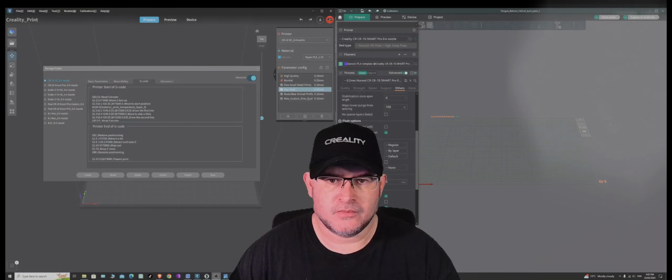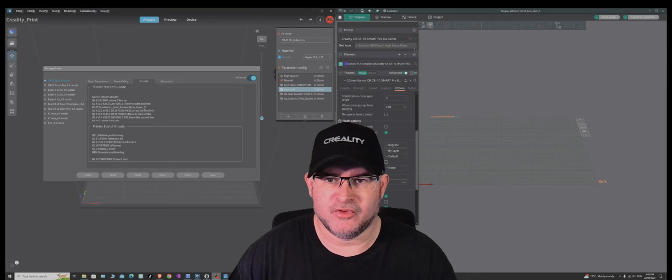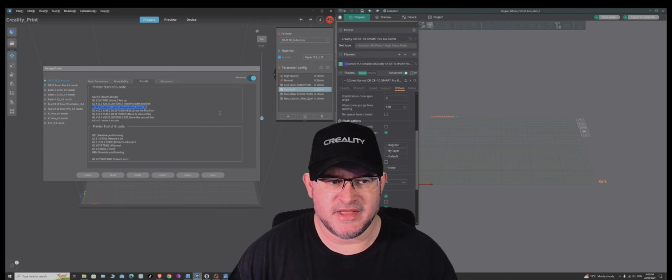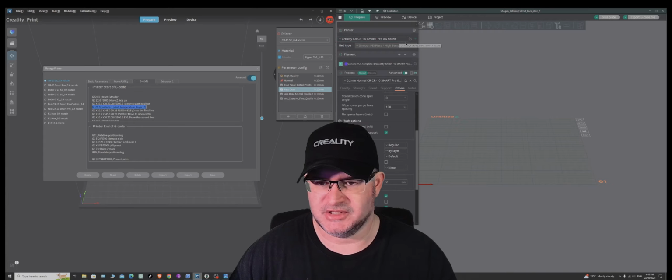Click out of here. All right, one of the other things I want to mention with the G-code before I go into these settings and we start entering a custom profile printer is, I'd missed a point to mention with this M109 material print temperature layer 0. One of the things you need to check, it doesn't always have to have the M190 in there, as other printers don't have them.